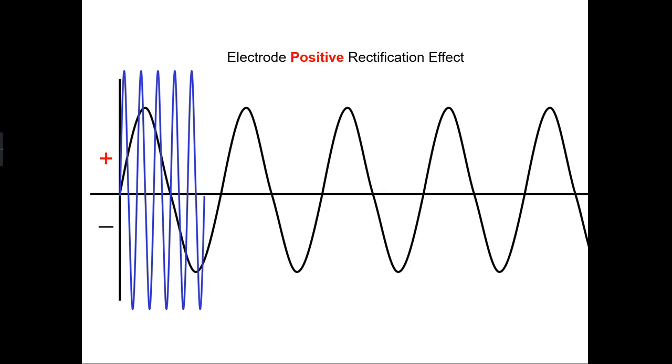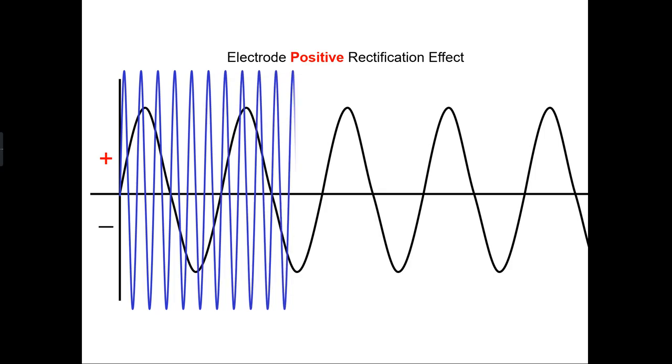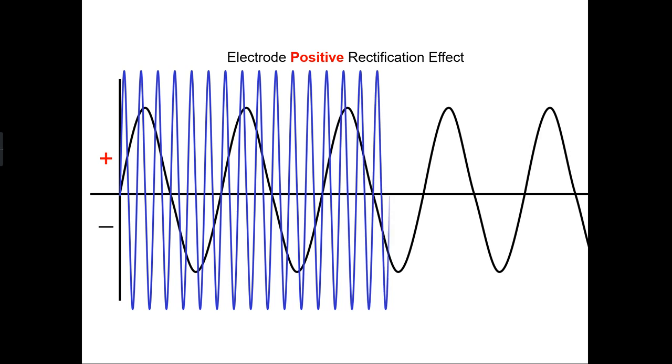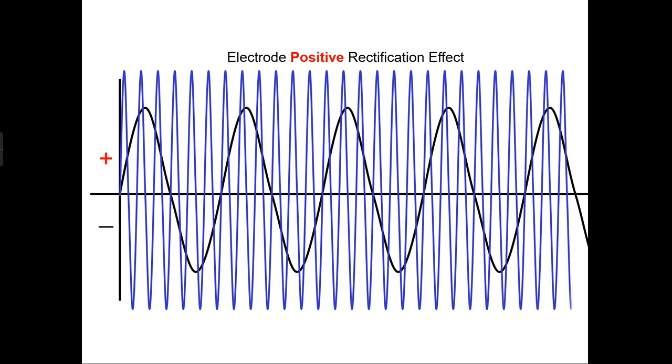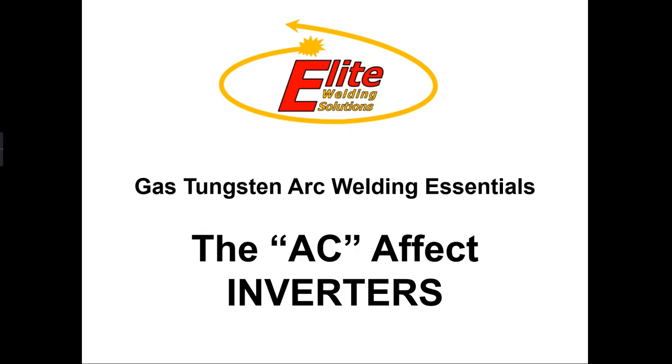So the high frequency that initiates our arc: I'm just putting this in place here to understand that when we TIG weld, we don't want to touch the surface. Depending on how your machine's set up, we don't want to touch the tungsten to the surface. We want to try avoiding that with something called high frequency start. A lot of machines are set up for touch start, but they're designed for touch start. This is something I'll talk to each individual company about, based on what their machines are set up to be used like.